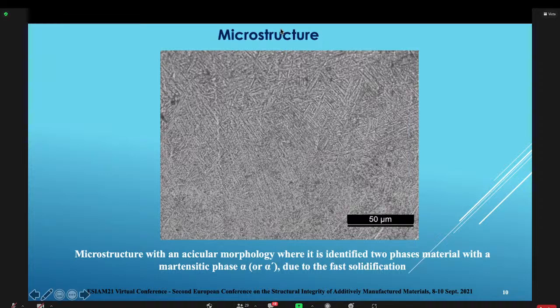Oh, that's a nice question. One of the methods that we used was made by finite element analysis, not using the DIC system. We analyzed more than 1,000 cases of position of the crack, and then we calculated the J integral, and with that we can calculate the crack parameters, the delta K parameters. Okay, but not with the DIC system. That will be very interesting to do in the future. Very interesting. Okay. Thank you.